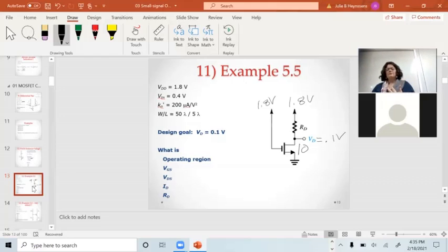Normally, this is a red flag to me. Transistors with small VDS are not in saturation. They're digital circuit switching circuits. In fact, this is what this is. This is a pass transistor.